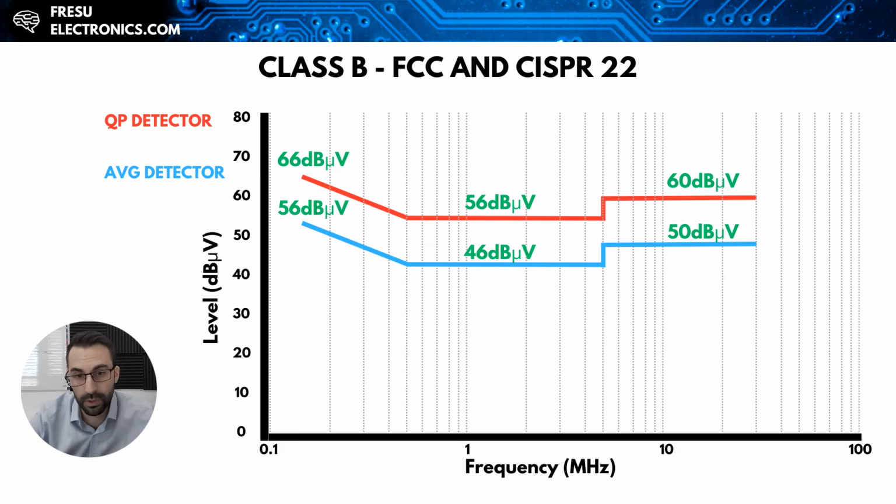One of the common approaches when doing pre-compliance testing before going to certifying at the EMC lab is to keep the system emissions at least 6 dB below the required limits. And this will help to account for the differences between different laboratories and instruments, also due to the measurement uncertainties. I personally recommend staying even below the 10 dB margin, if possible even below the 15 dB margin. However, I know that this is sometimes very difficult to attain, so 6 dB is a common practice.